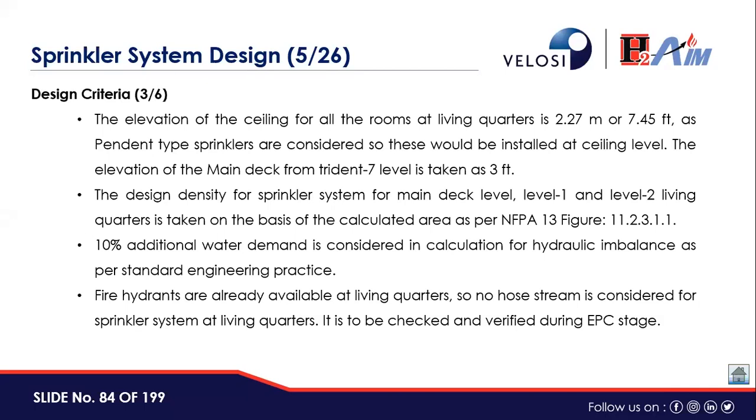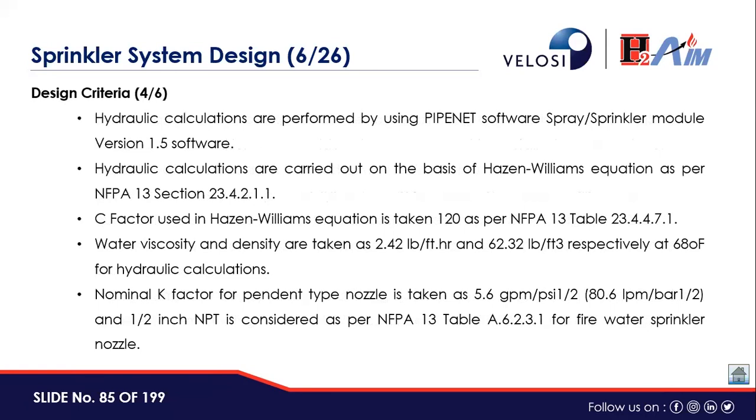10% additional water demand is considered in calculation for hydraulic imbalance as per standard engineering practice. Fire hydrants are already available at living quarters, so no hose stream is considered for the sprinkler system at living quarters. It is to be checked and verified during the EPC stage.